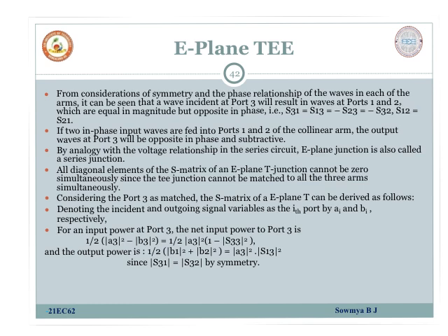Whenever we want to check the output, one port is treated as input and another as output, and the third one will be matched terminated. So all cannot be matched terminated simultaneously. Hence, all the diagonal elements of the S matrix of the E-plane junction cannot be 0 simultaneously.